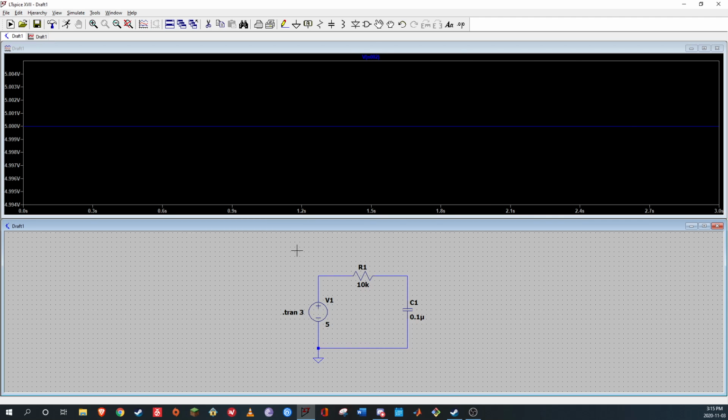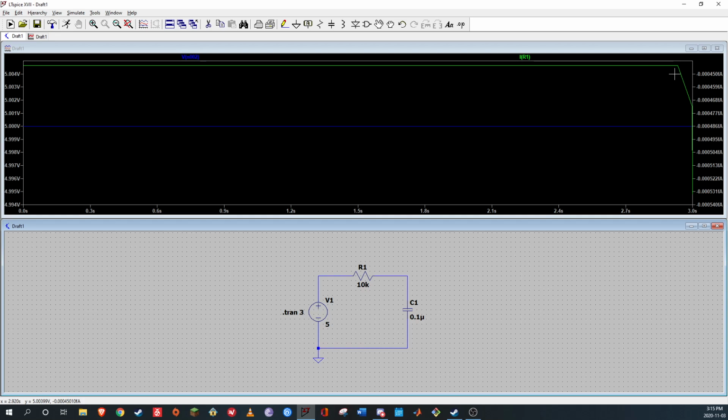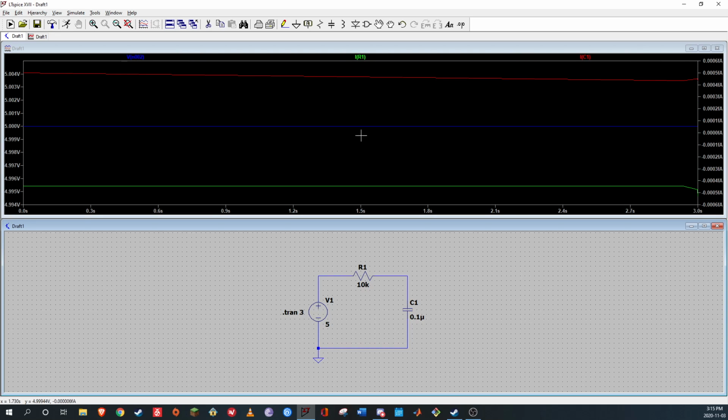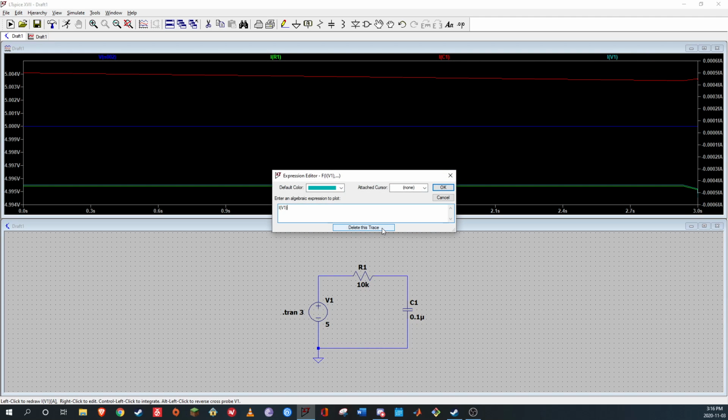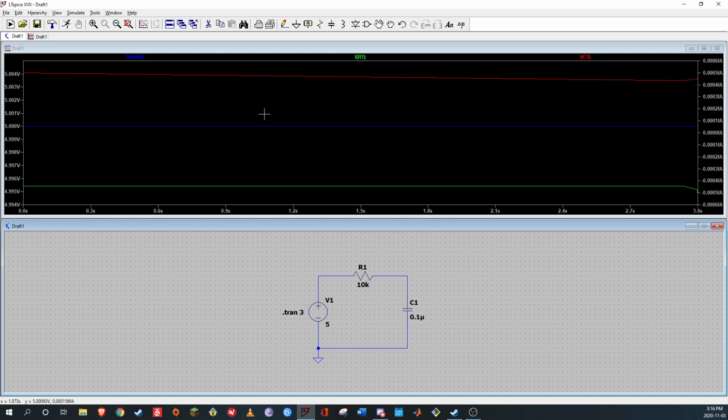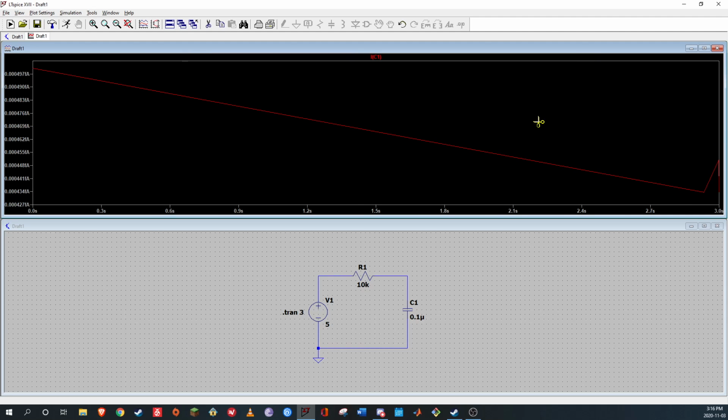So this basic circuit's not really doing much, but you can see that your current is pretty different by clicking on the current through the resistor. Same with the current through the capacitor. You can see that they're actually opposite, which is kind of what you would expect for a capacitor and a resistor. Now we got a whole bunch of traces here, and maybe we saw something that was a little confusing and we just wanted to see capacitor current. So if you want to get rid of traces, you could just go up here and hit delete trace. Or you could select the whole window and just hit delete, and it'll give you these scissors, and you can just go through and say, okay, I don't want to see the current in the resistor, and I don't care about the voltage. So now all you can see is the capacitor current.